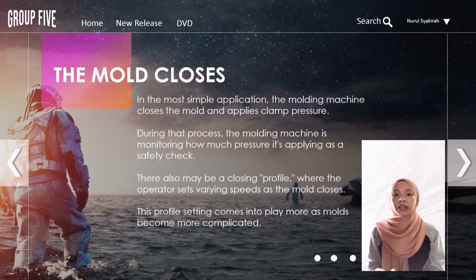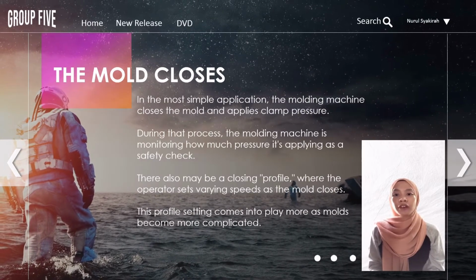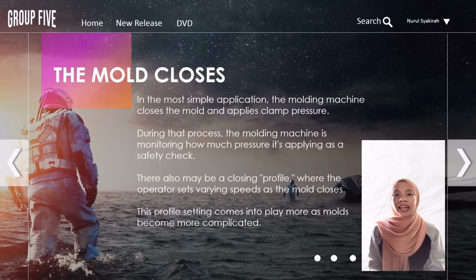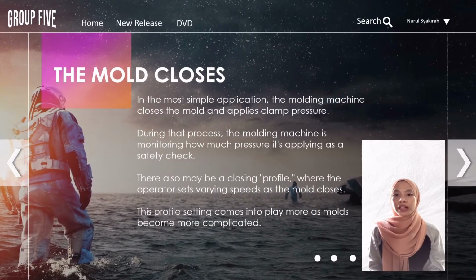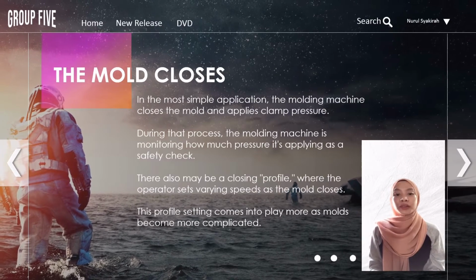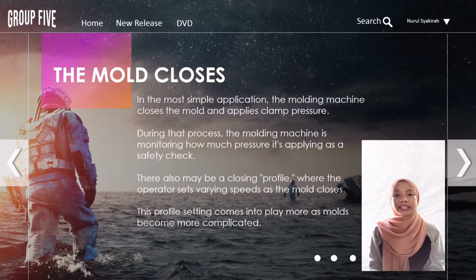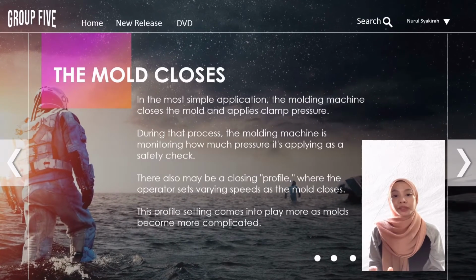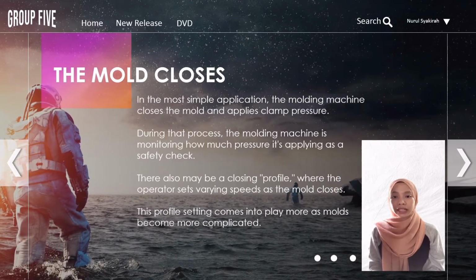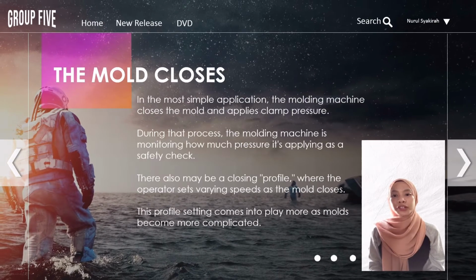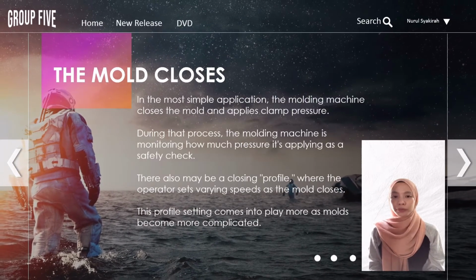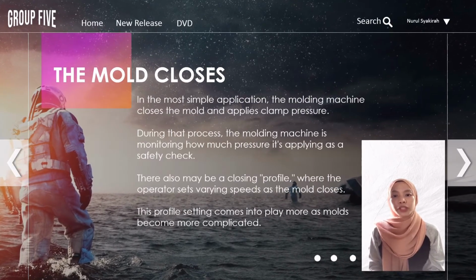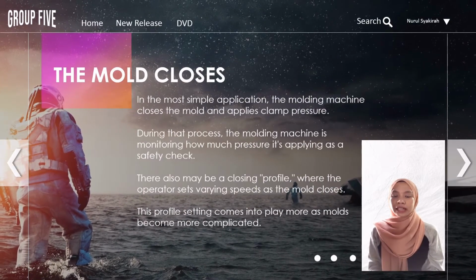In more advanced applications, we have actuation of hydraulic core motions inside the mold and unscrewing operations. That works in tandem with the mold close operation. They may operate off time, position, and machinery with the mold. Overall, it is important to find a balance between fast closing time and safety.